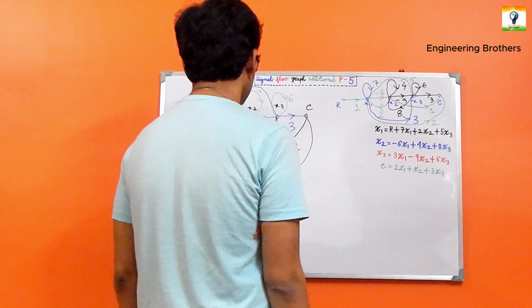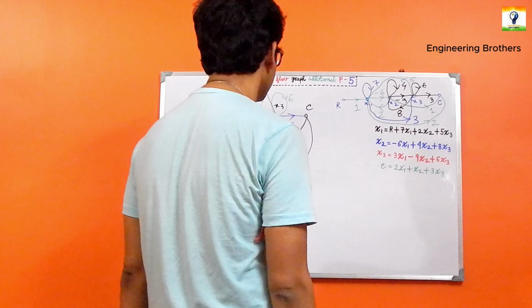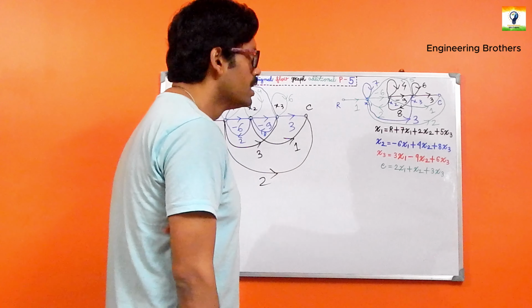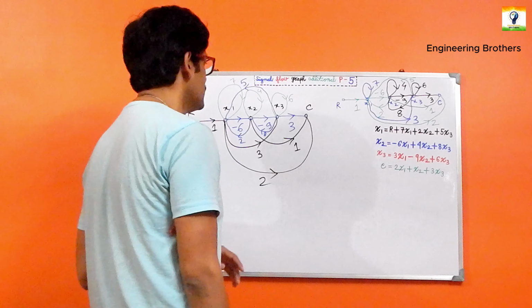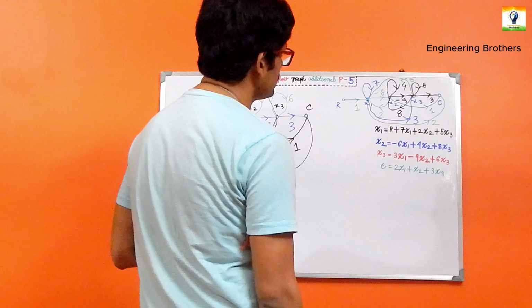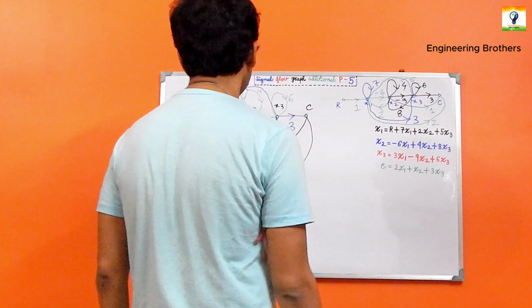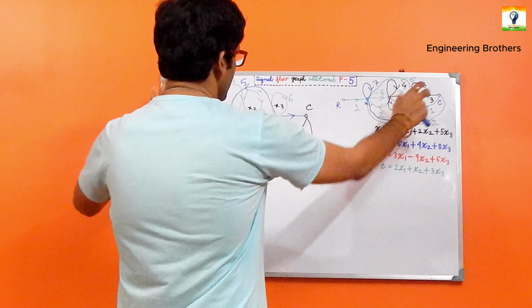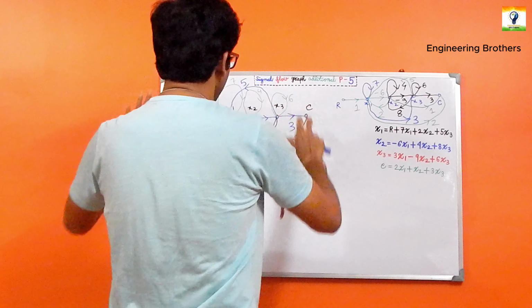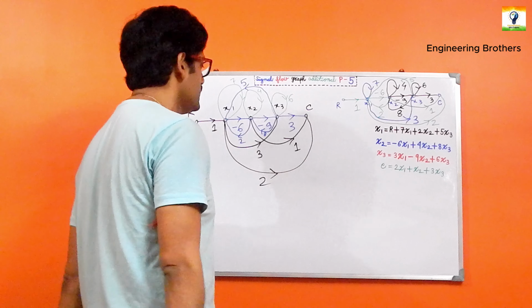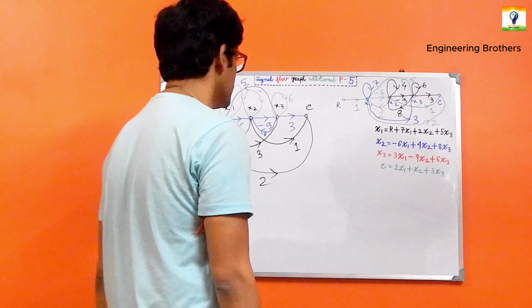Okay, and this is our overall picture over here, and let us just check whether any part of our loop or any part of our forward path has been missing. And I don't see any missing link or missing path over here. I have totally considered the total diagram, and magnifying this on the left-hand side of our diagram, this is going to be our final signal flow graph.